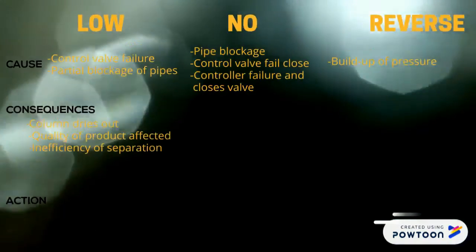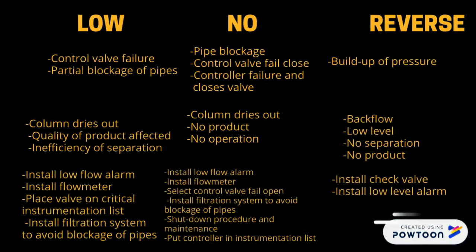For no flow meter, what will cause is pipe blockage, control valve will fail close, controller failure and closes valve. And consequences are column will dry out, no product and no operation. What we need to do is install flow meter and low flow alarm.